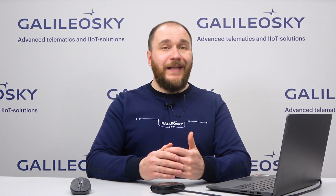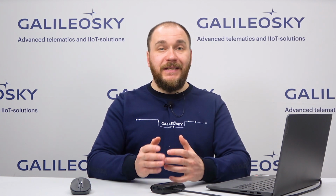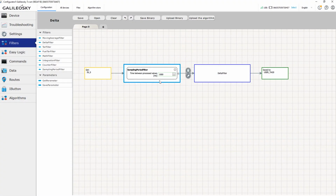When using this filter, please pay attention to how often the original value updates. For instance, if you'd like to track the voltage change on the analog input using this filter, the result will most likely be about 0. Trackers measure input voltage up to 8000 times per second. It means that the difference between two values will be small. But again, you can use sampling period for setting the interval.